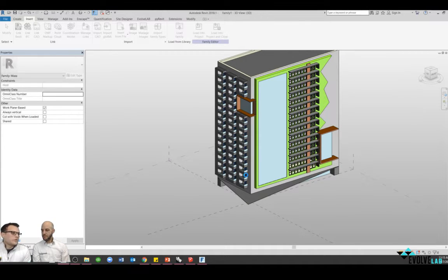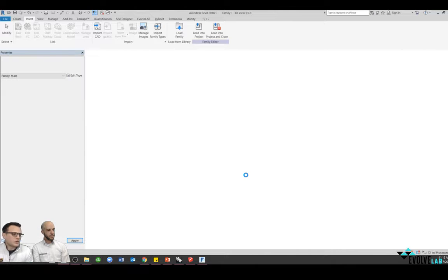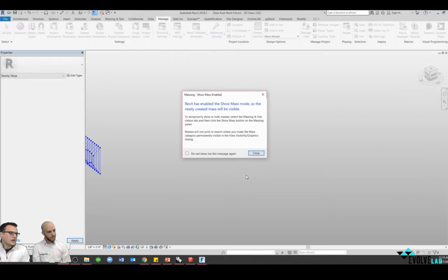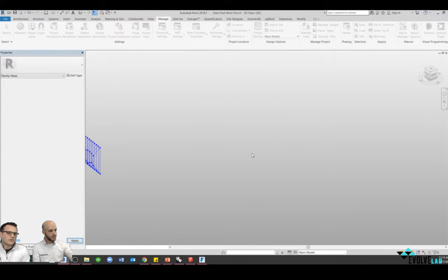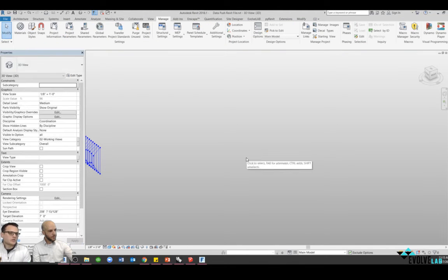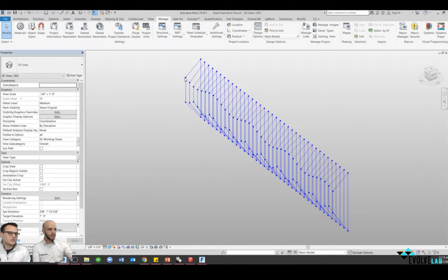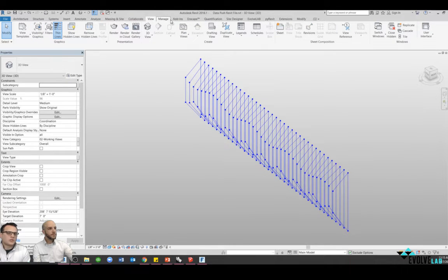This is a really good workflow actually for dealing sometimes with doubly curved and complex geometries that might have been authored in a totally different software. One of the things you can do with this specific workflow is you can associate walls and other native components to the face of that imported geometry itself. So this workflow definitely has its use case, but it's not necessarily a direct interoperability. There is some sort of step in between, and that's something to remember for the specific scenario where you might have a complex geometry that you can't build natively for whatever reason.